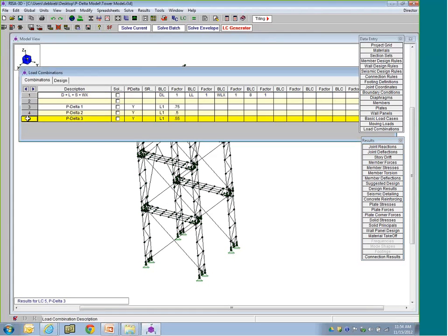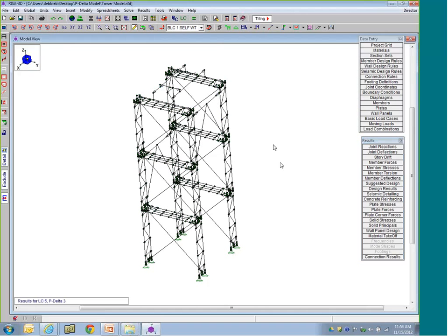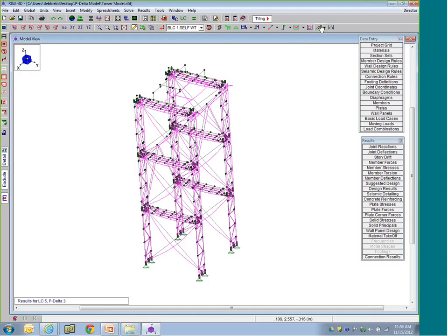So if everybody understands, what I did is I just pulled the entire load combination 1, and I just started reducing the factor. So every single one of these is being reduced by 3/4, then half, then 0.55. Okay, and that one looks like just a nice amount so we can see exactly what's going wrong. So now I can actually show it did get past the P-delta, so let's see what's going on with just a little bit of that P-delta turned on.